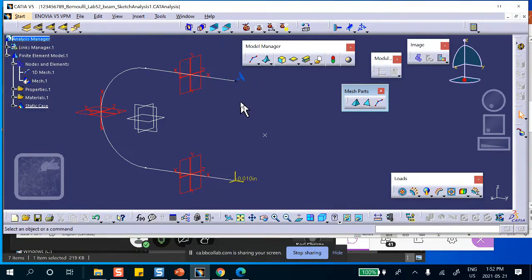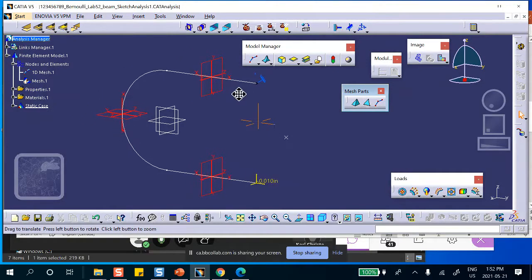The other thing is that when we did the solid problem, we said that the face is shifted down by 0.01. Here, we don't have the luxury of saying the face. The face is basically represented by that single point. So we're going to say we apply a downward displacement to that point.